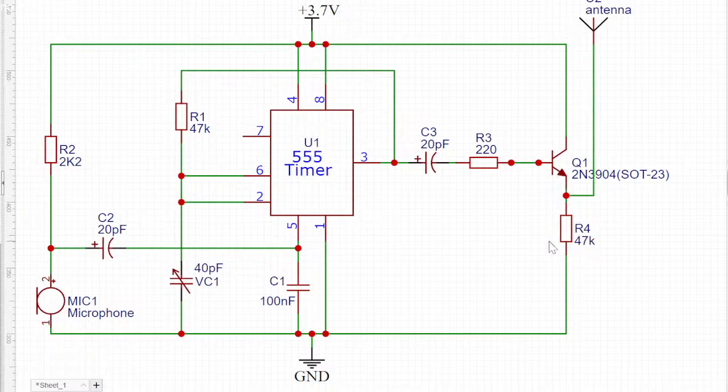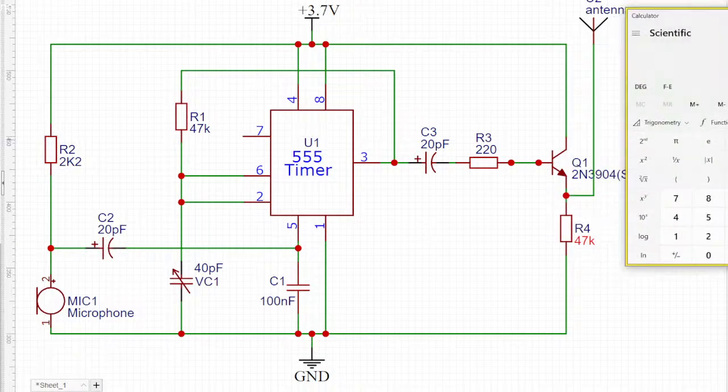But if you choose a collector current, or quiescent current, of maybe 0.1 milliamp, then you calculate the value of your resistor. So why do I choose the value? I want it to be drawing little to no current when there is no load. So I'm going to find a value for my resistor.